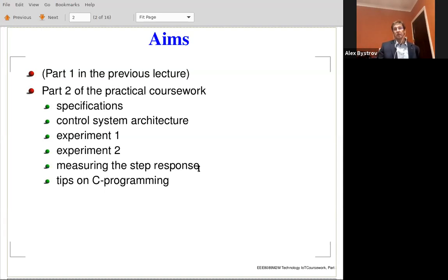So if the system is stable and it has time to settle down between those periods of experiments, that's why I suggest to have 5 seconds separation between going from 0 to 1, from 1 to 0. A sufficiently long separation, then it will be just a series of automatically constructed, generated experiments with the step response.